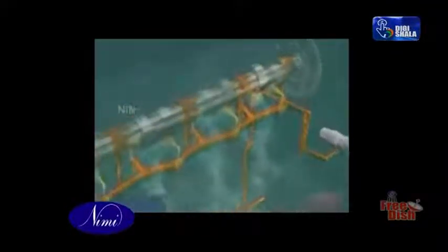Full film lubrication. An oil film is maintained by forcing the oil between the surfaces by an oil pump. The main parts of the lubricating system are the pump, driven by the camshaft. The pump forces the oil from the sump to the main oil gallery. This runs across the length of the engine. Drillings from the gallery allow oil to be supplied to the bearing surfaces.